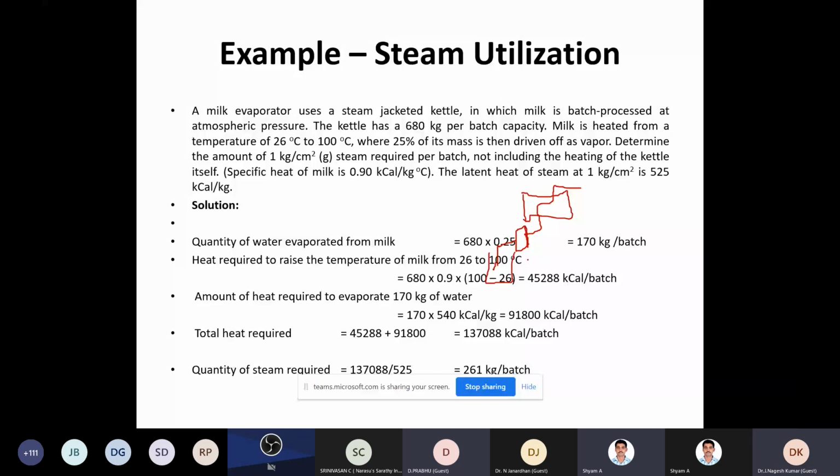So how will it indicate the steam consumption? It is the law of conservation of mass. Whatever steam enters here, the mass of steam entering the heat exchanger is equal to the mass leaving the heat exchanger. So entering mass and exiting mass are the same. So the mass of condensate flowing here is nothing but the mass of steam that was sent here. In practice we actually do this kind of collection. Open out the trap, put a hose, bring it to a collection tank, and then we measure the amount of steam consumed in the equipment.